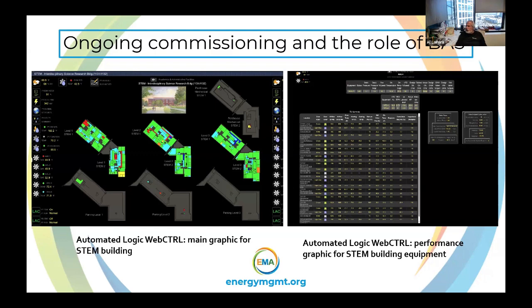Yeah. So have you considered the idea, and I think you and I talked about it briefly, just doing an overlay and then putting in what I affectionately call protocol converters, which are like JACEs, where you can bring it in and you have an overlay, whether it's Delta or ALC or whoever you pick as your overlay, that ultimately, when you bid it out, is that another route you were thinking? So this way you could bring it all together and still have 5 different or 7 or I don't know how many different systems.